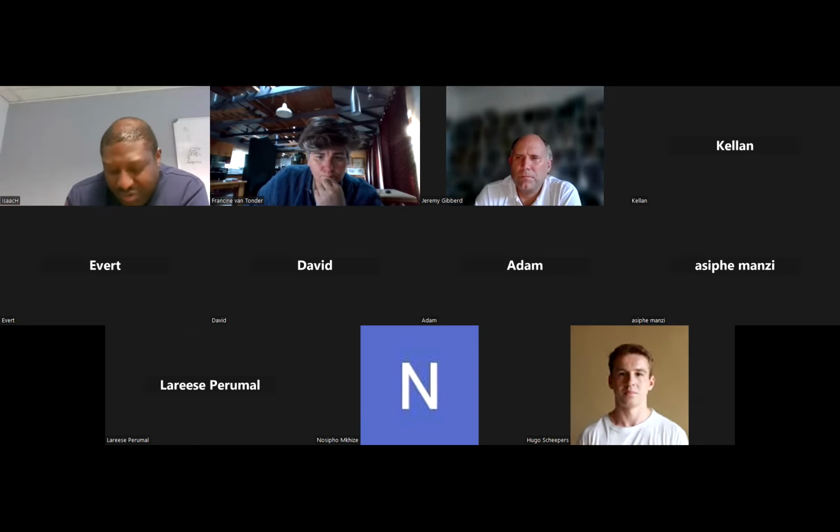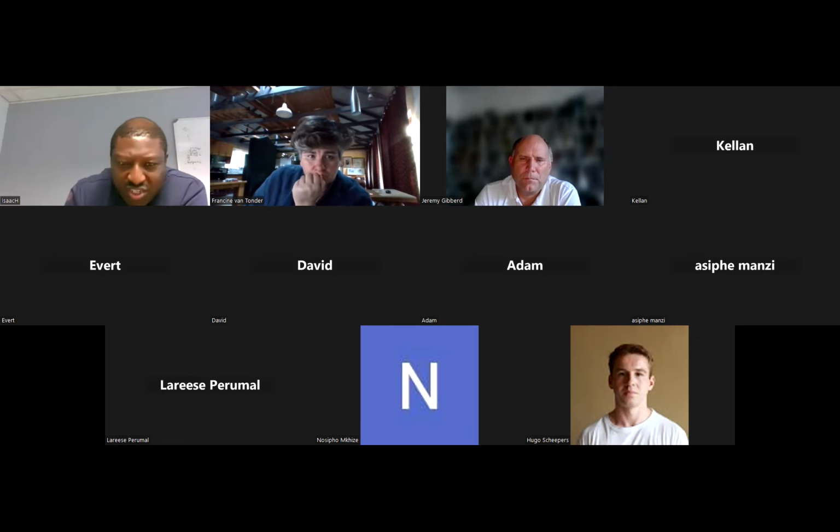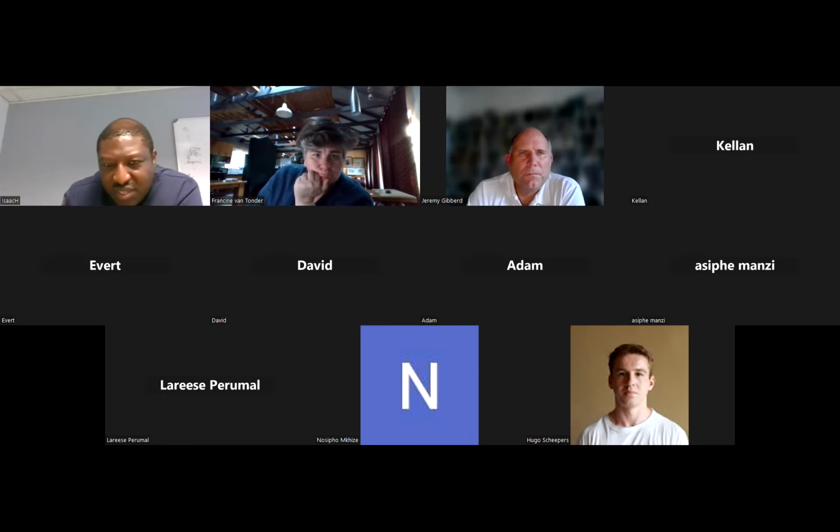In my opinion, I'd advise students to go extreme in design. There are no limitations, as long as they understand the means of compliance as written in SANS 10400 A2, means of compliance. If they can comply through rational design, Agrément certification, rational assessment, or deemed-to-satisfy, then they're good to go.